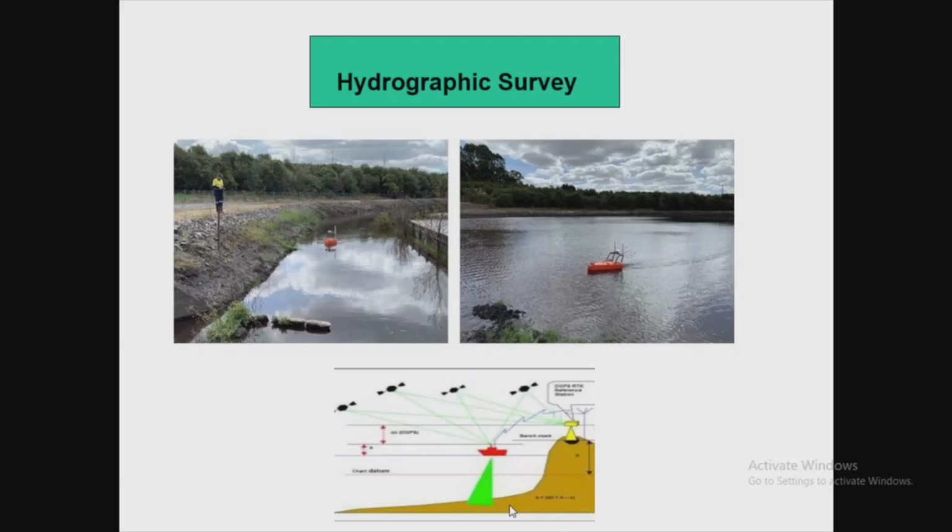It depends upon the DGPS, the quality of DGPS you are using, the quality of the echo sounder type equipment you are using, and the quality of beam you are using for penetrating the soft bed and hard bed. Then only, and specialized manpower is required for that. And this is the proven method, because you will get the exact capacity which is reduced, or the exact capacity of sediment which is deposited.